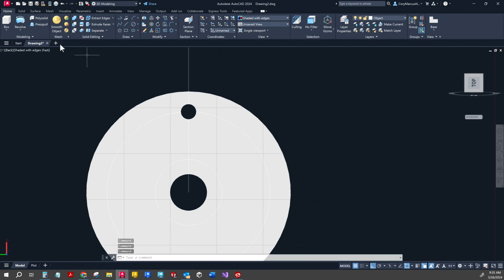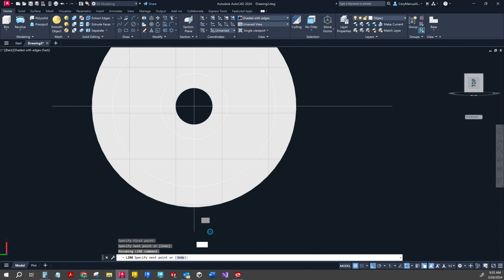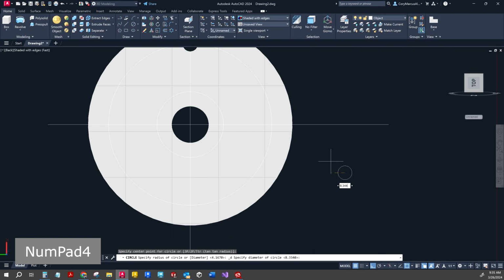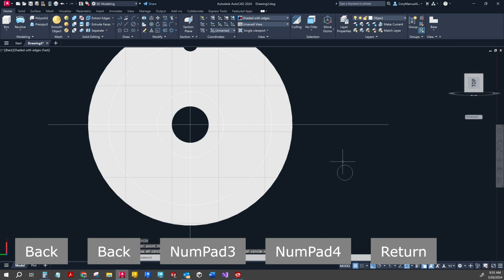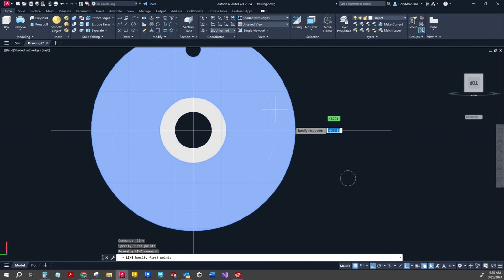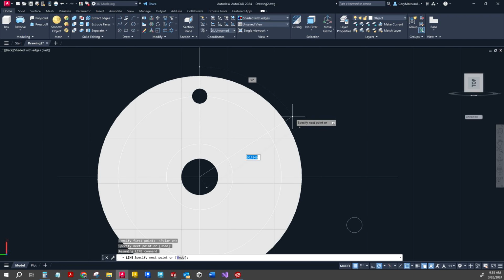It's the same process, so we can just do a line that goes this way, and I'm going to draw these relatively sloppy because we don't have to keep this sketch geometry. It's just for construction. So we'll draw a circle out in space that is 8.334. And we're going to need to make these equal. So we know the quadrants, right? That's pretty straightforward. From here, we want to put the snap on 45, 90, 135, 180. Make sure you get that green projection when it snaps.